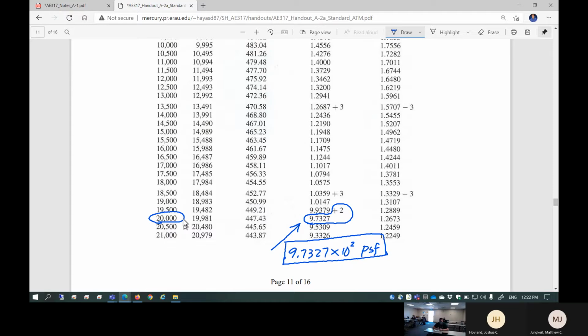It could be a massively non-standard day. Heavy rain, snow, very high or low temperature, right by a big mountain, right by the ocean. I don't know. We never know. 20,000 feet is just an estimate. So you're not going to trust it, but you know the pressure instead. That's called pressure altitude. Let's go back.